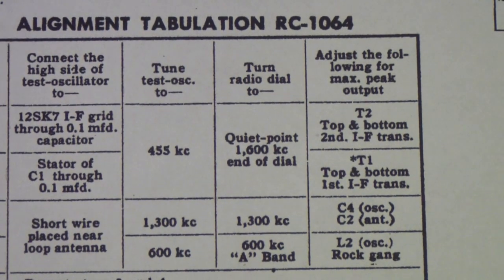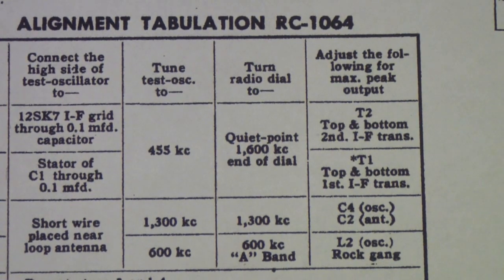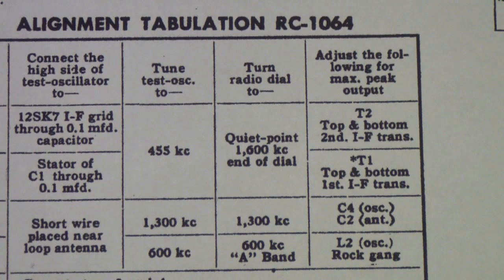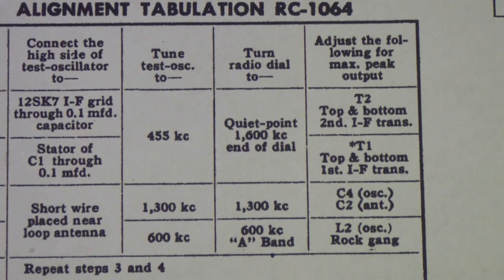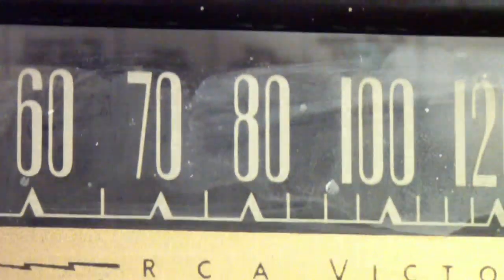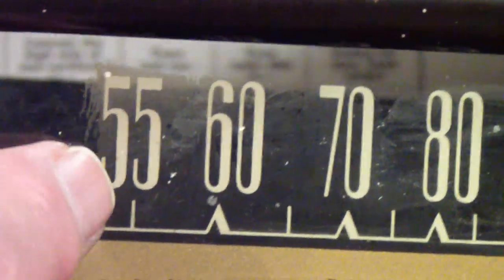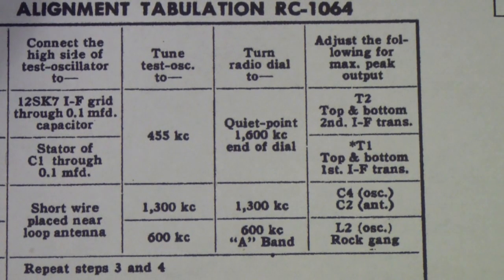Now, these All-American 5s were notorious for having nonlinear dials, and often the way they were designed, somebody would build the receiver, align it as best they could, and then they would make the markings on the dial. In other words, they would put off doing the artwork for this dial until last, until they knew where the needle needed to be for these various markings.